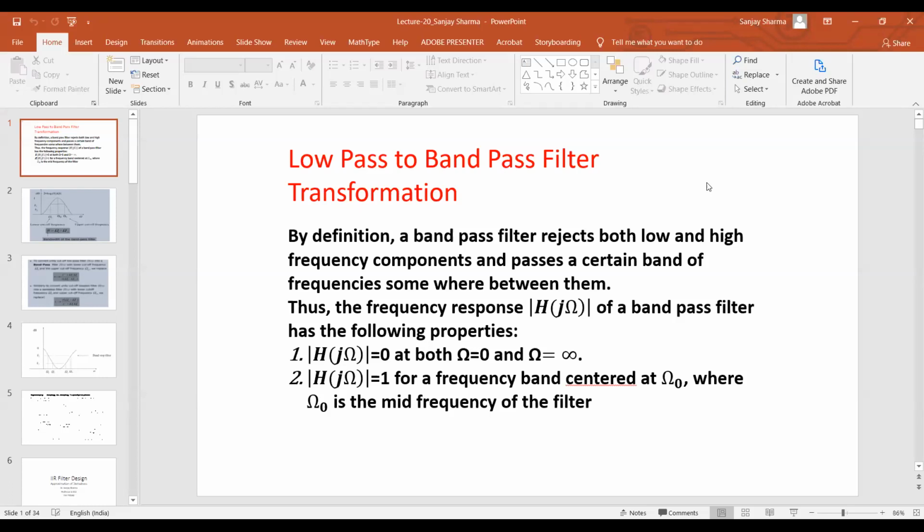But today I will start with, because we also know that the strategy to design filters is to create the equations for low pass filter prototype, and from the low pass filter prototype we will use the transformations to get the high pass filter or band pass or band stop filter. So today I will start from the slides in which from the low pass filter prototype, I'm at present talking about the Butterworth filters only.